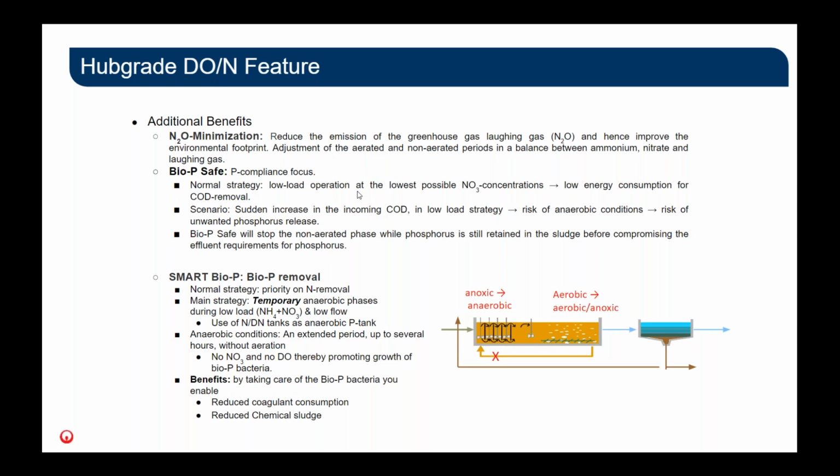The DO and N control is well suited to allow facilities, because it's a continuous monitoring of both ammonia and nitrate, and controlling aerobic and anoxic events. There is also a RAS control feature and an internal mixed liquor recycle control feature.